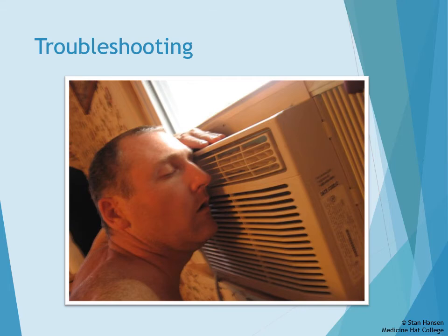If you do have voltage between the R and the C, the next thing to check is to turn on the thermostat to cool and turn down the thermostat in order to close the cool switch. Then go outside and see if you have 24 volts coming up to the power relay. If you have 24 volts across the coil of the power relay, then everything should be working, but there's going to be a problem with the power relay unit itself, and that needs to be changed.